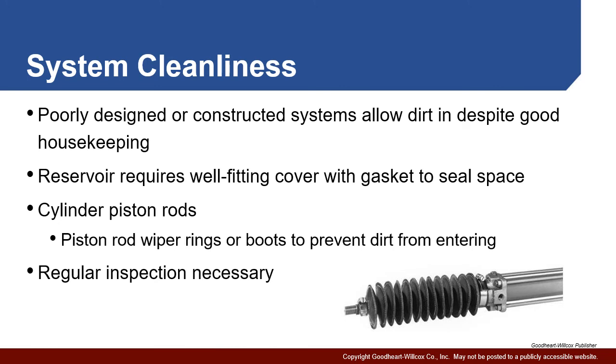One way to prevent this from getting in is to keep the reservoir relatively sealed. Right? There's usually going to be a well-sealed environment where there is a vent, but that vent is going to have filters on it as well. One of the common places where contaminants come in, particularly with construction equipment, is where the cylinder extends and retracts. This is one of the few places where a component is going to be exposed to the environment and then taken internally. So we're going to have a number of different types of wiper seals on a cylinder, or if we're definitely going to be in a very dirty environment, we may want to use a boot of some type over the top of the cylinder that prevents that dirt from getting into the system.